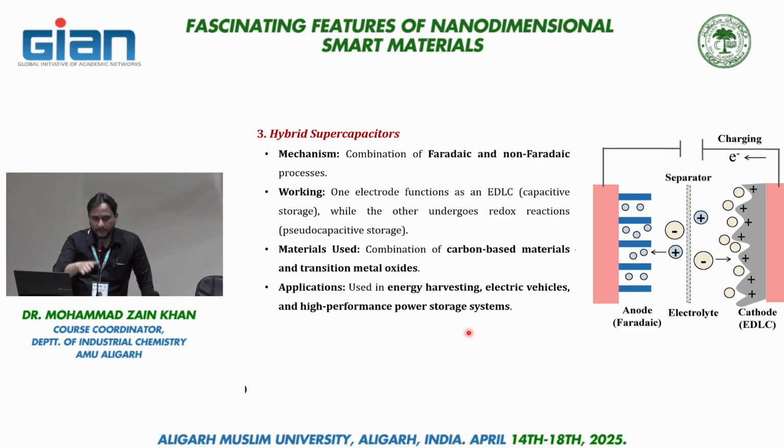So in hybrid supercapacitors, we have both phenomena, Faradaic and non-Faradaic. Depending upon the type of material and the conditions, there may be more Faradaic phenomena as compared to non-Faradaic, or on the other hand, we may have more non-Faradaic phenomena. It depends upon the nature of the material as well as the conditions. But in hybrid supercapacitors, we have both phenomena occurring at a time, the Faradaic process as well as the non-Faradaic process.